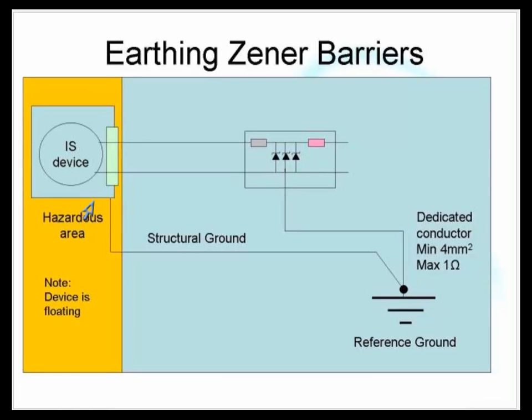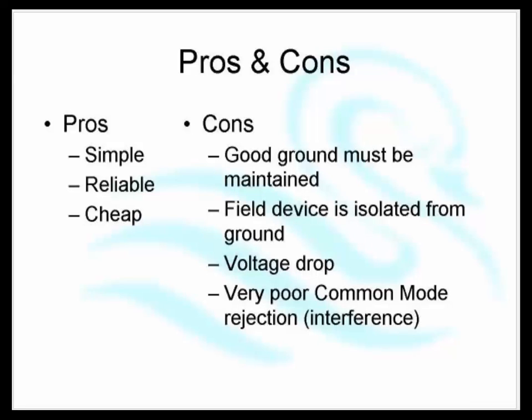This leads to a few other little problems. It leads to a thing called common mode rejection. Basically, it picks up noise. It picks up mobile phones, it picks up fluoros, it picks up noisy two-ways, it picks up every piece of noise that's floating around. So it tends to make for a very noisy signal.